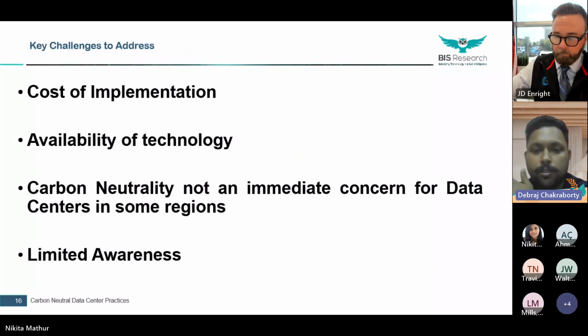Of course, the other types of technologies, let's say D2C and some in-rack and in-row liquid cooling solutions, can be retrofitted. However, if we are looking at a power density capacity of more than 20 kilowatts, you are going to require immersion cooling. Beyond that level, nothing is going to be more efficient than immersion cooling.